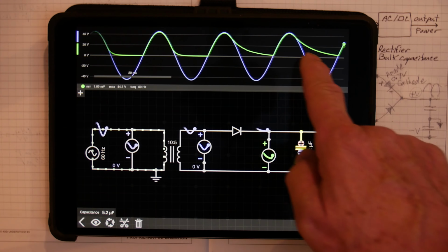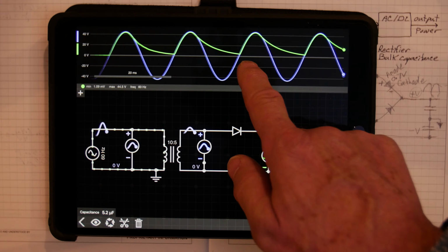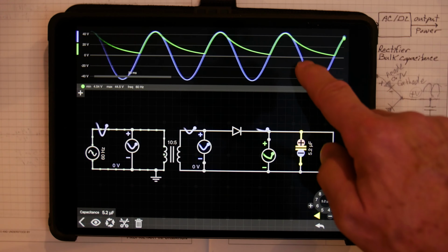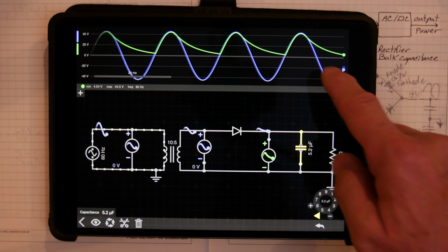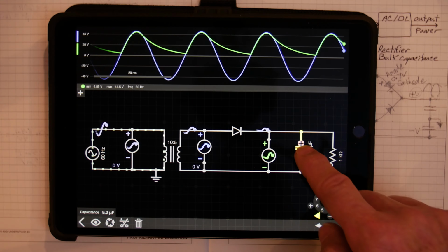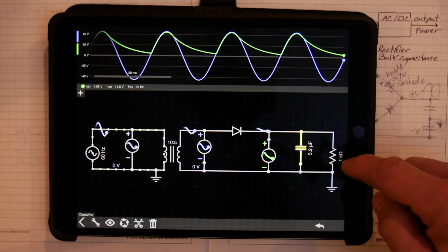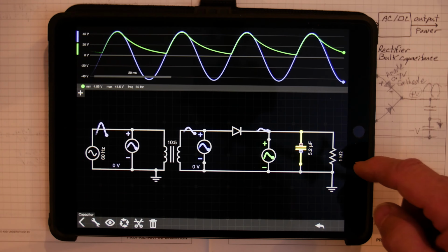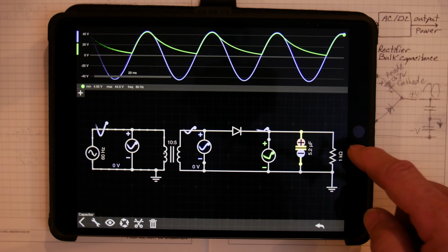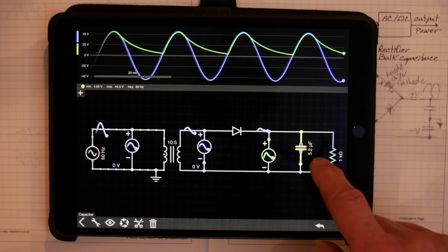So at 5 microfarads, you can see that now it's got a longer charge, but still, it's almost down to 0 before the next waveform comes up again. Every time we get a charge waveform, it charges the cap back up. But then it discharges pretty quickly. So 5 microfarads isn't very big. I mean, we only have a 1K ohm resistor pulling a load off of that, but that was approximately, well, it's about 44.5 milliamps. So it's not very much.